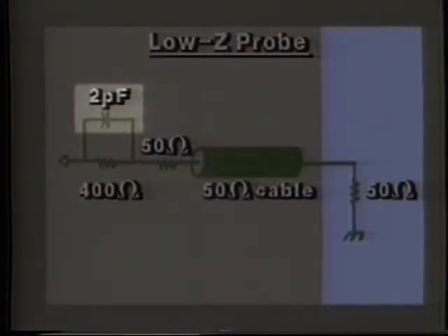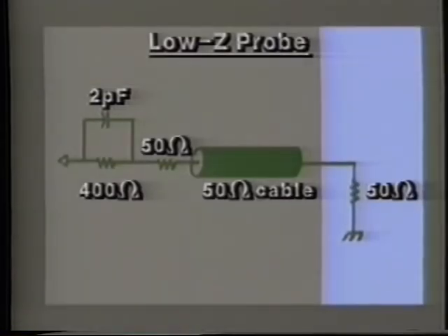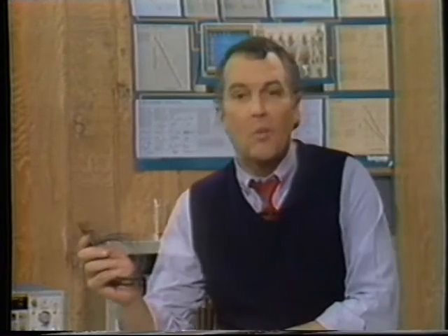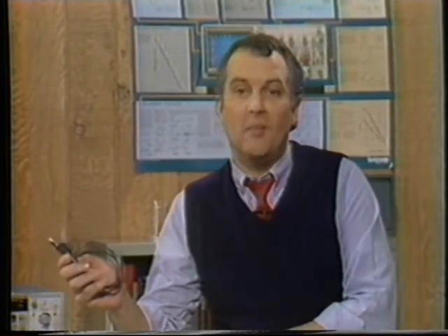No, that capacitor in the tip is not part of a divider. It's a peaking network to compensate for skin effect losses in the cable at very high frequency. The C in of this probe consists primarily of parasitics present in the mechanical geometry of the tip. Remember, nothing's ideal. It's actually quite low, about 1 pF. Now, you might say, what a dandy probe. At last, something I can use all the time.